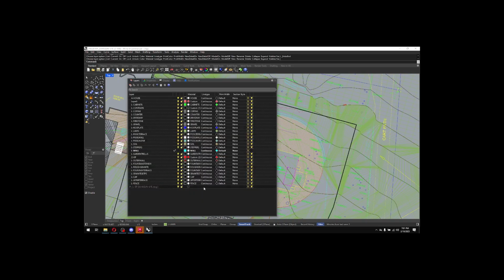Work session. If you need to get rid of that, right-click on here, work session reference, detach model. If it's anything other than a CAD plan and you change it somewhere else, I don't really run into this a lot, but sometimes I'll build things in Rhino, it could be a house or multiple buildings, and an architect sent it to me. I'll keep that file as is and also work session the Rhino file in. Then if somebody makes an update to that, I can hit update work session reference, and it'll automatically update whatever changes were made in the other file. You can't do that with CAD. For some reason, they've never made it so you can just hit update. You have to detach and reattach.